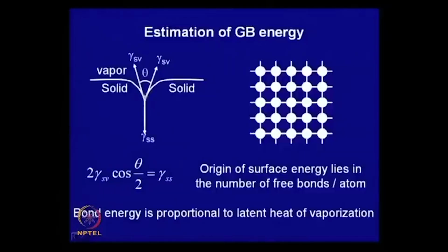The grain boundaries get etched, and when you look under a microscope or with a profilometer, you can follow the profile. You will find that at the grain boundary there is a dip like this, and you can take a section, draw a line and measure the angle between the 2 grains, or in a profilometer reading it is also possible to measure this angle.